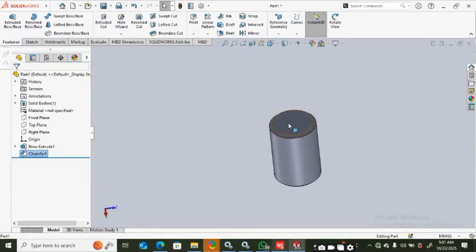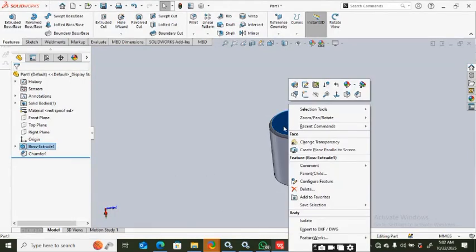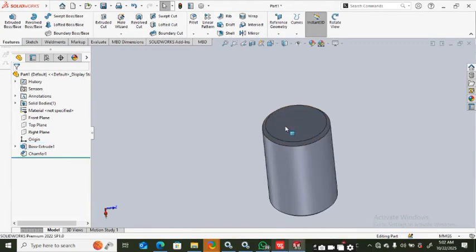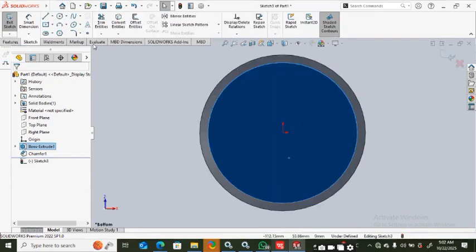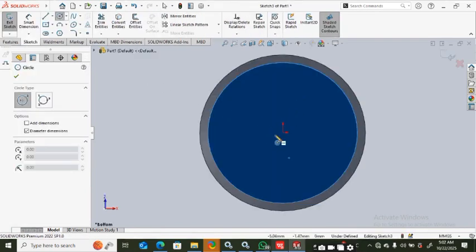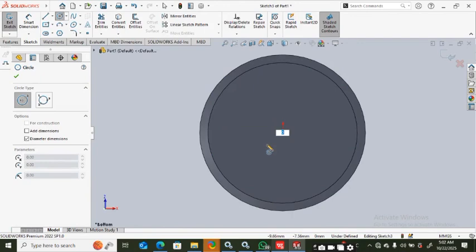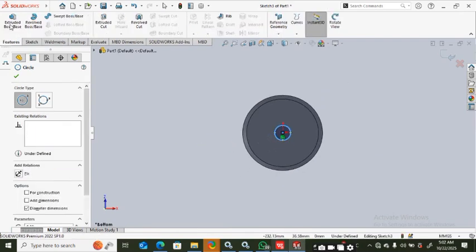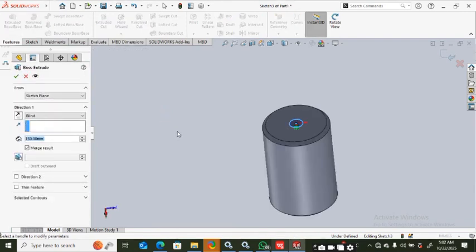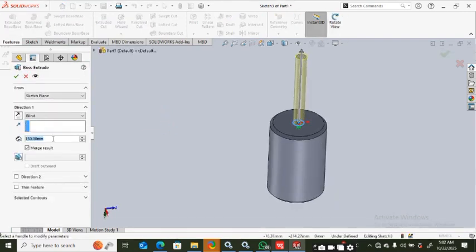Now we'll click the surface, make the surface a plane where you do your sketch. So you're going to click your sketch. Now you go to your keyboard, you dial in 20, you press enter, and then you move to your extrude. It is extruded to 16 millimeter, and then that's it.